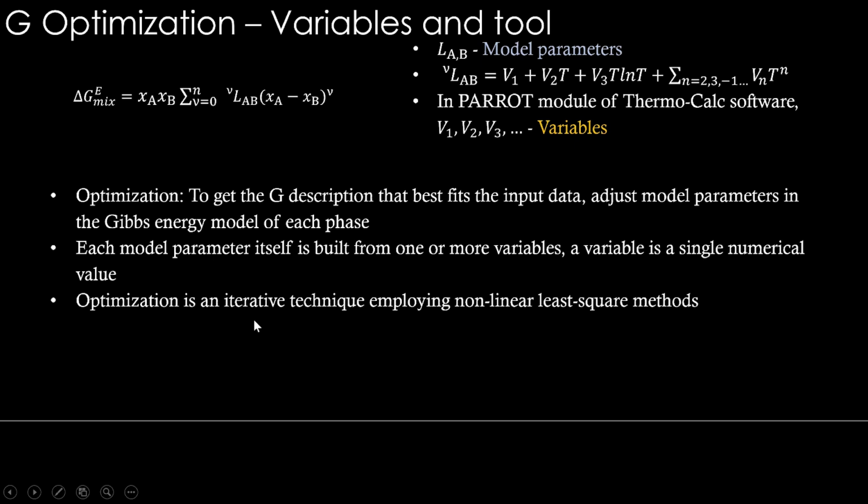And optimization is an iterative technique employing non-linear least square methods, and this particular method is incorporated into the routines of the Parrot module in the Thermo-Calc software. That's the tool we are going to use, the Parrot module of Thermo-Calc software, and we have to use console mode for this.